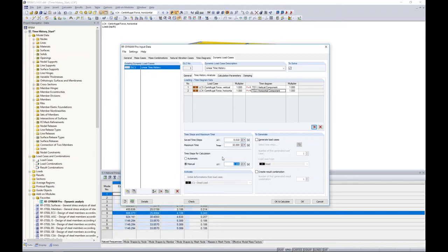So way back in the PowerPoint, I had mentioned a suggestion of a time step equal to or less than 1/20 times our frequency. Now remember, the frequency is the largest frequency from either the excitation or my natural vibration analysis. In our case, this was exactly the same, at around 25.8. So this comes out to about 0.001 seconds. We can create a result combination here, as I mentioned, so this will just give us an envelope solution for all of our time steps considered.